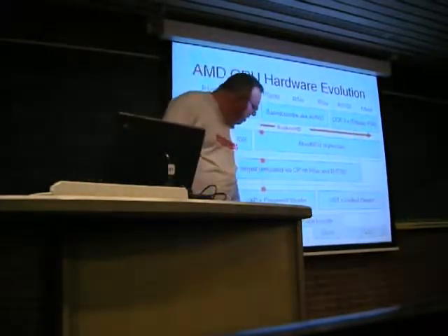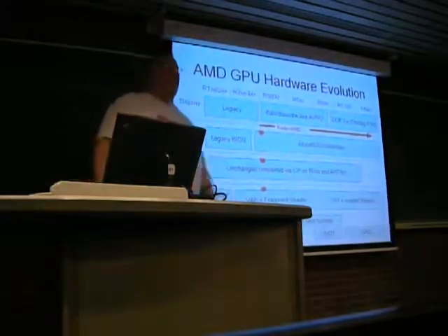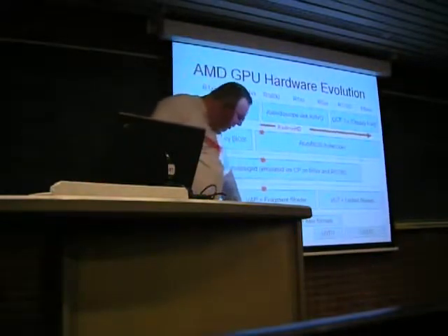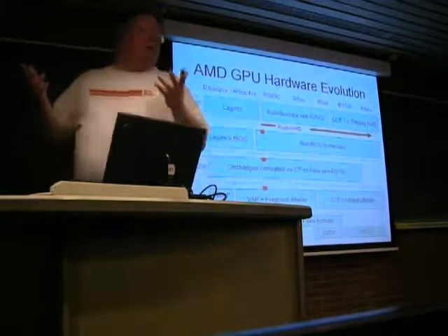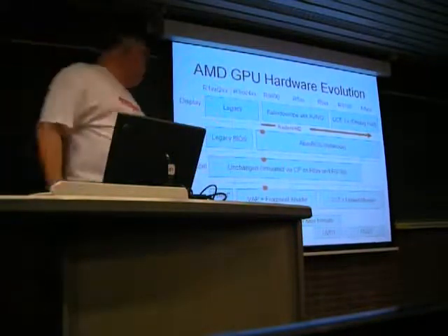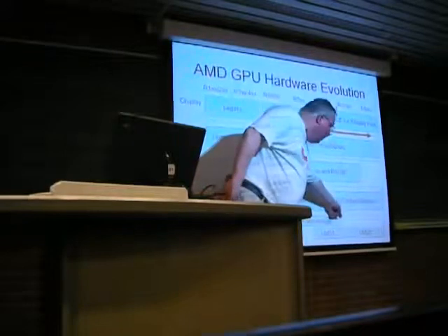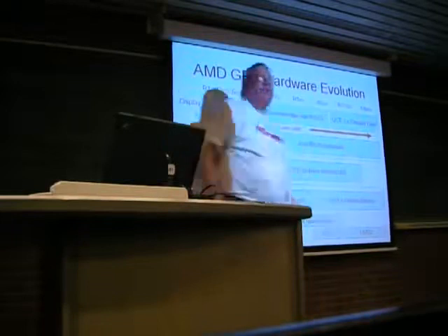There's dedicated hardware in there for IDCT that's been around for a while, since before the Radeon. It changes in the sense that the way you program it and synchronize it is different. It picks up new video formats and stuff, and it persists all the way to the end of the 6XX line. Okay? 780 is the first chip that does not have the legacy IDCT.